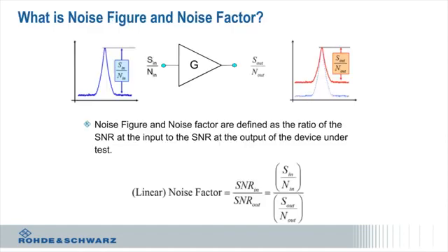So when we design a system, the key is that when you receive a signal, in an ideal world, if you look at the previous slide, my noise floor is at minus 114 dBm in that 1 megahertz channel. I don't want my system to add any more noise to that. So ideally, I'd be able to pick out a signal slightly above that minus 114 dBm, but perhaps just slightly above it. But the reality is, if you've done engineering, you know that there's no perfect system. So when you put in an amplifier, which is typically near the front end of a system, it's going to add some noise. Anything that's an active device will add some noise.